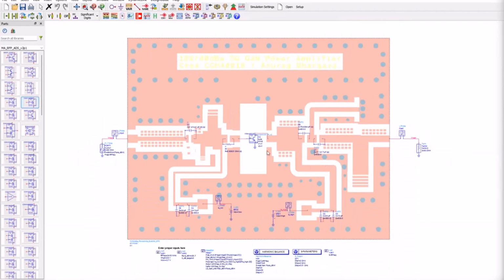Now, depending upon how you route, how you put things together, where you put the bend, how you squeeze the size to minimum, will make an impact on your eventual RF performance. So doing this kind of EM circuit co-simulation is a very, very crucial part, because when you do circuit simulations, it doesn't take care of parasitic coupling.